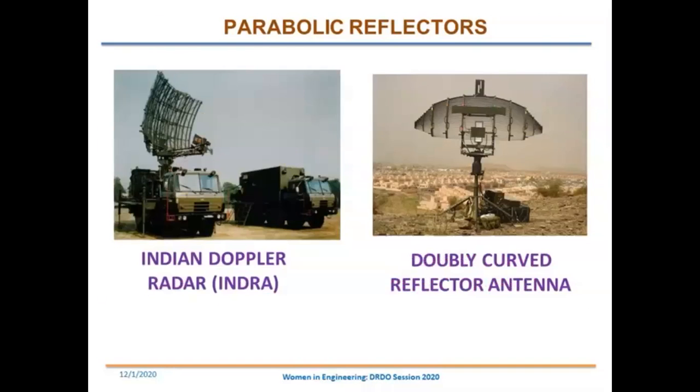One more thing I wanted to tell the audience is that antenna design is a combination of electromagnetic, mechanical, as well as fabrication professions, if it is a microstrip based antenna. For example, this antenna has to be packed in a rope. It should be able to be carried by a human being in a mountainous region, or transported by animals like mules or donkeys. Since this was at L band, it had to be mechanically thought out how the weight can be optimized, how it can be made fittable, and then it had to be quickly deployed. Those constraints are there from the mechanical side. And after doing that, our electromagnetic performance should also not be affected. That is one of the challenges when we are designing an antenna.